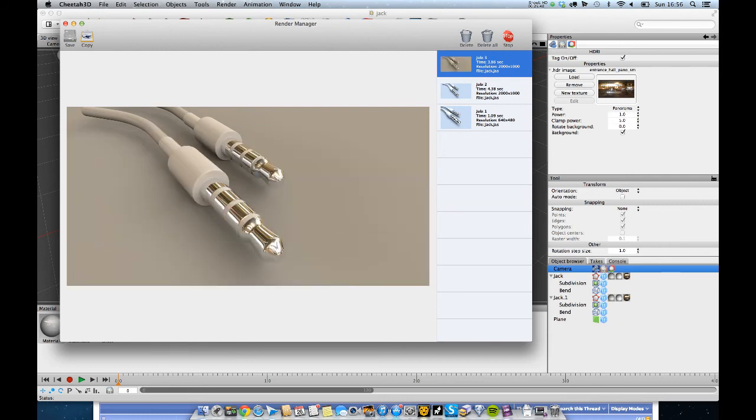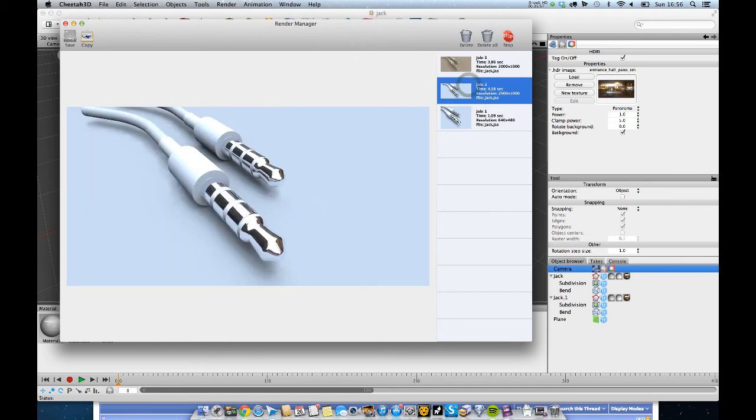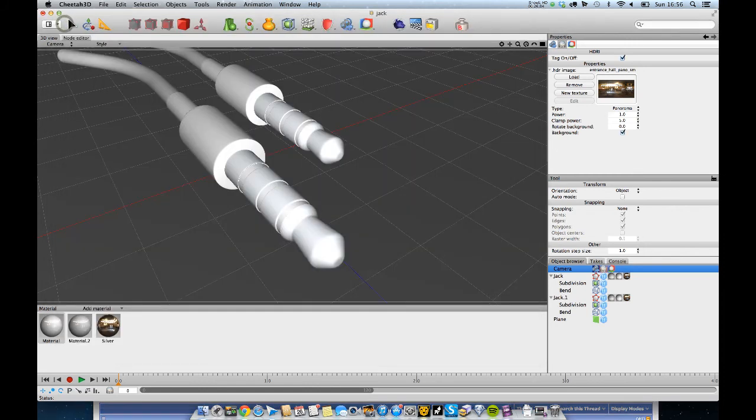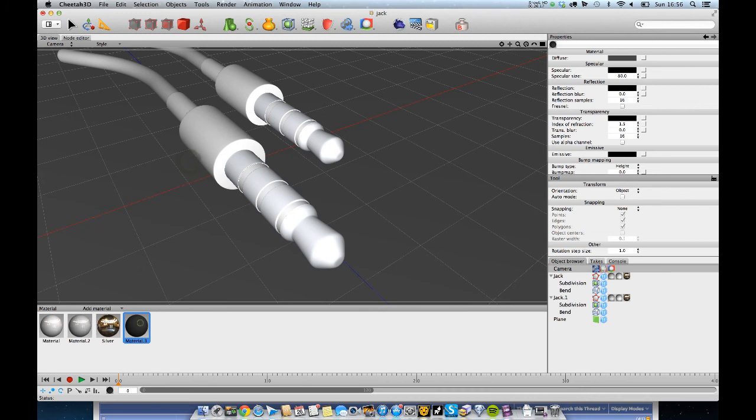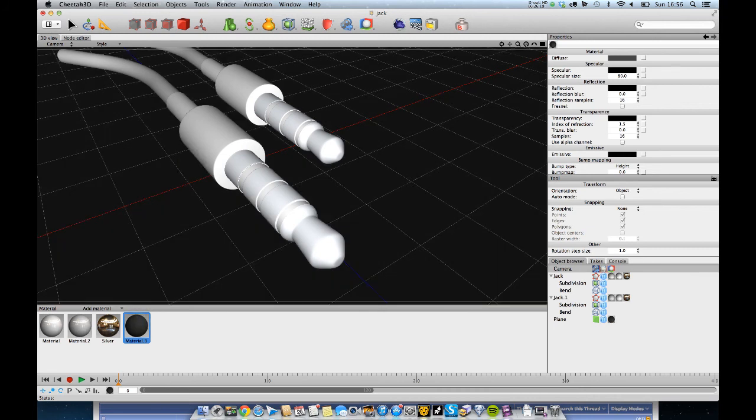And now we start to get the weird gold wash. Okay. Just looking at the chrome mainly, I kind of like the chrome on this one. I don't like the blue wash, and it's a little bit bleached out. I'm going to solve some of that by firstly adding a new material, which is going to be my floor. I'm going to go for quite a dark grey with no specular whatsoever. Let's pull that down. Throw that onto the floor.